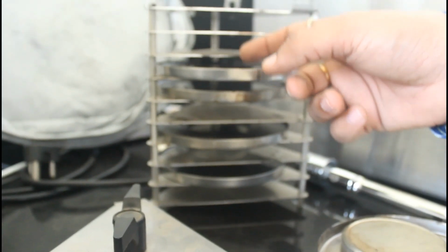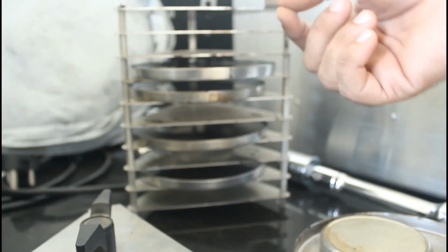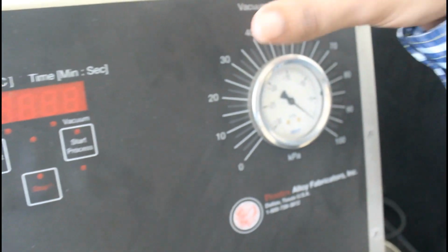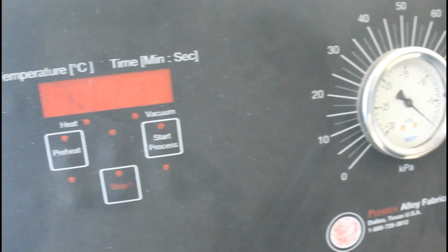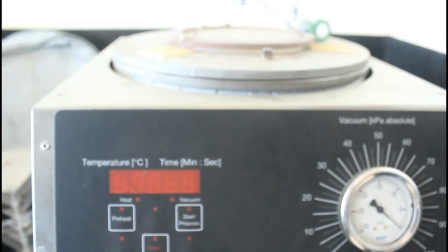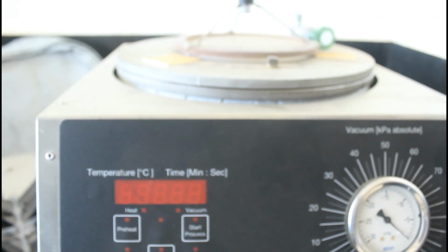Once we do this long-term aging, the bitumen from the PAV vessel will be quite liquid, and it will have some gases also. These gases must be removed. To remove them, we immediately transfer it to the vacuum degassing chamber. This chamber applies a small amount of vacuum and removes all the gases from the bitumen. Once the gases are removed, the bitumen can be tested further or stored for later testing. This way the components of the PAV have been designed to simulate the long-term aging that happens in field conditions.